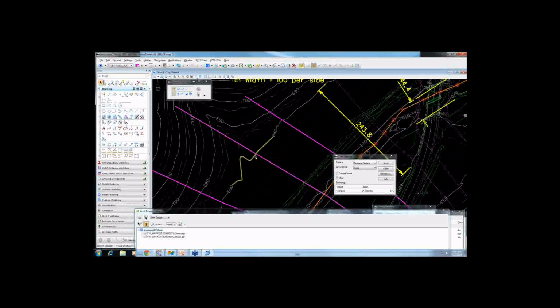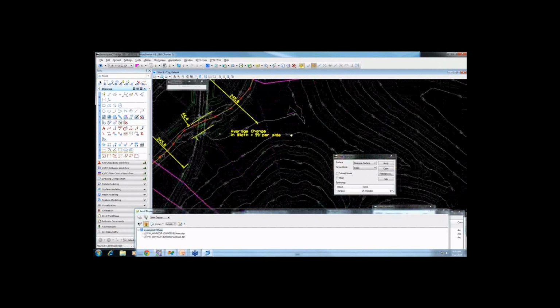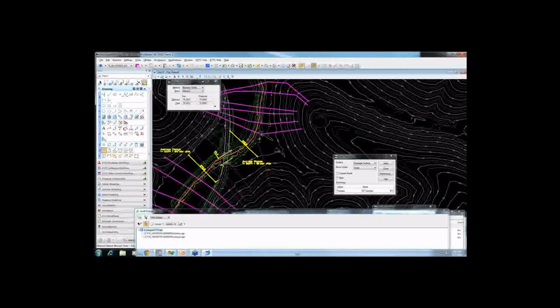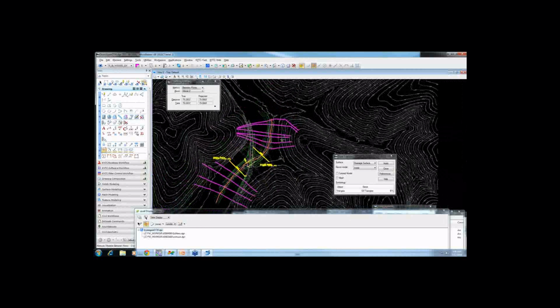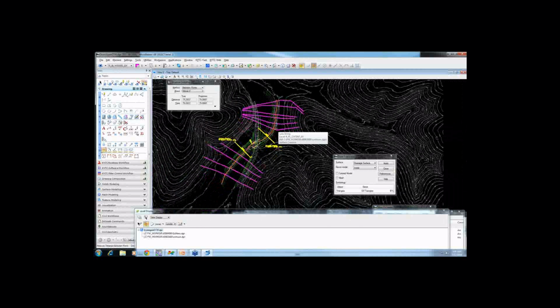If my water only gets up to 680, it probably won't matter. If my water gets up to 690, then I might be adding another 80 feet to the floodplain or something. So, there may be stuff like this where you have to figure out how am I going to avoid this, or if I have to put a cross-section there, maybe I need ineffective flow or something. So you just want to be aware of where you're putting your cross-sections and what that's telling HEC RAS.